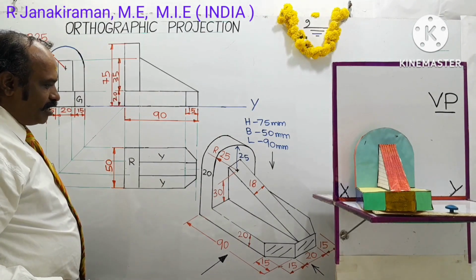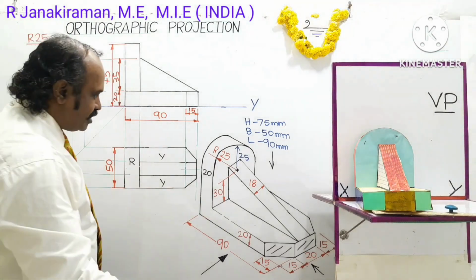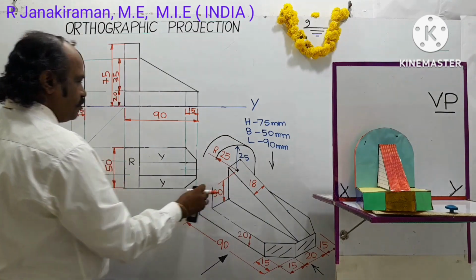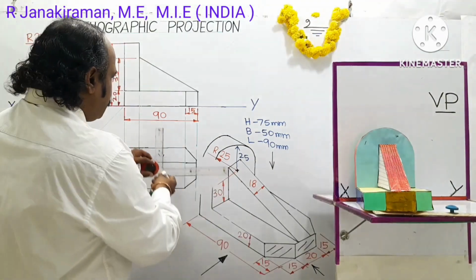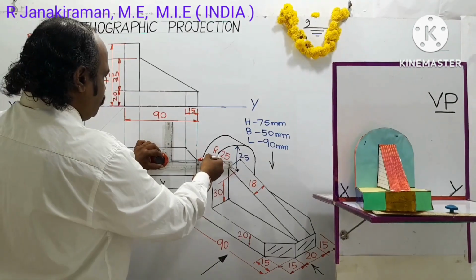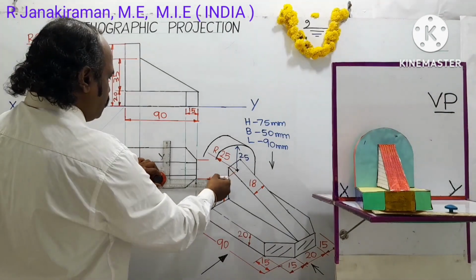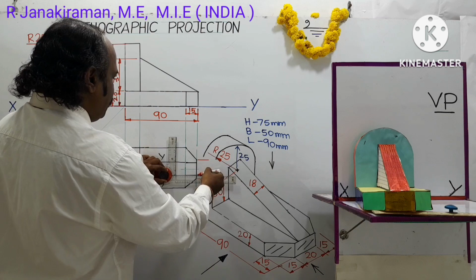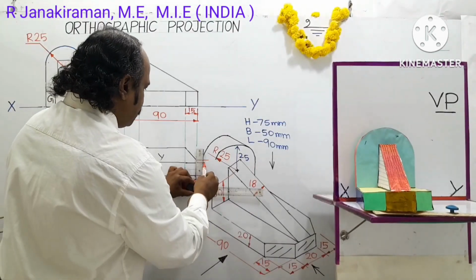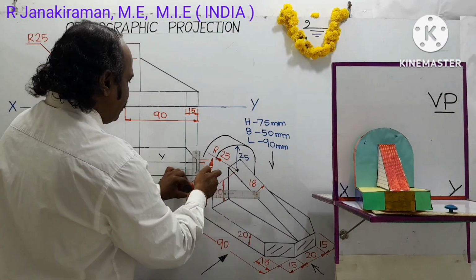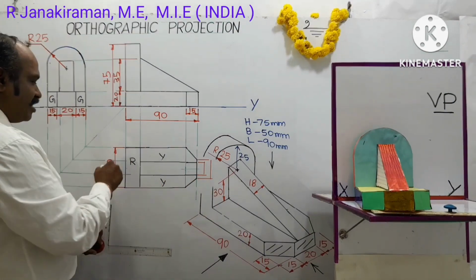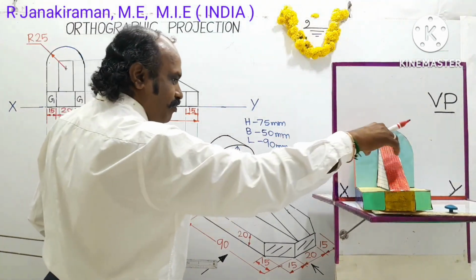It's incomplete. Let me erase this small portion of this 3D diagram. Using the longer scale of the drafter, draw an extension line. So this distance is the base thickness of the triangular part, 18 mm. This is 18. Then you draw again one parallel dimension line like this. Overall breadth is 50. So this is the top view.